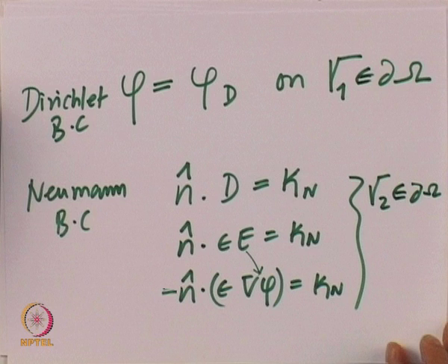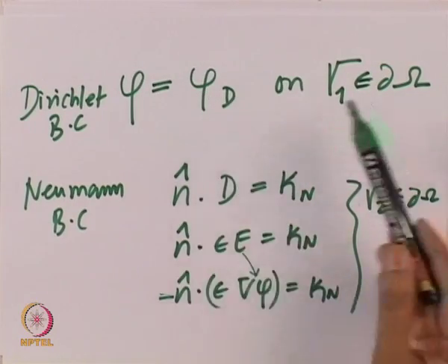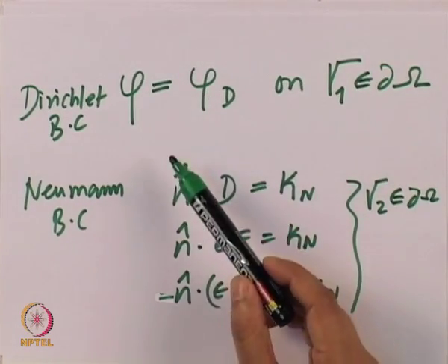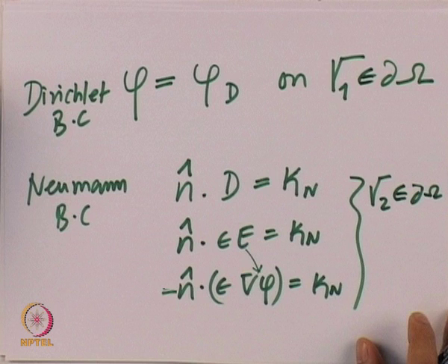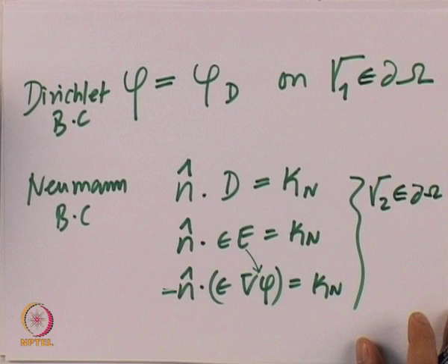For simplicity, in our case we can also say the value of phi equal to 0 at the boundaries. When we do the simulation we will use that condition, but this is a more general way of looking at the problem. The problem is defined, we have got the governing equations, given by this equation here, and we now have the boundary conditions, which are given by this equation.